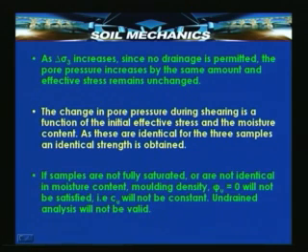Now, if we are having a sample which is not fully saturated, then phi u equal to 0 will not apply and Cu will not be constant. Undrained analysis cannot be conducted.